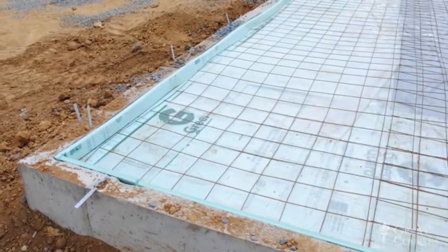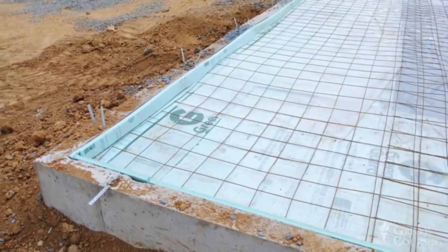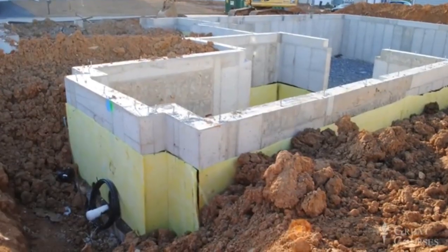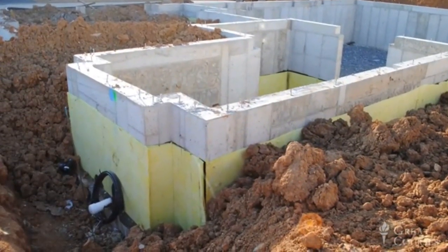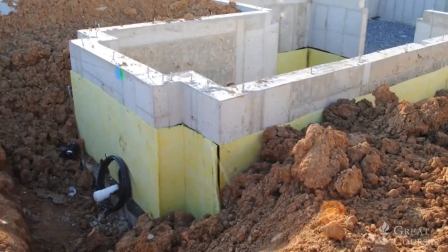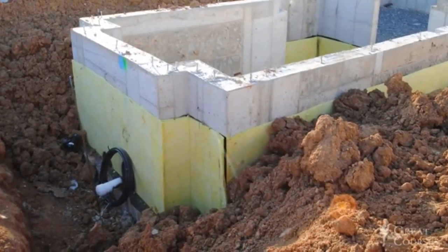Slab insulation is placed on the ground and around the perimeter before the concrete is poured. And foundation wall insulation is ideally adhered to the outside of the cast concrete after the exterior sealant has been applied and before the excavation is backfilled. In both cases, extruded polystyrene foam is generally used because of its good moisture resistance.